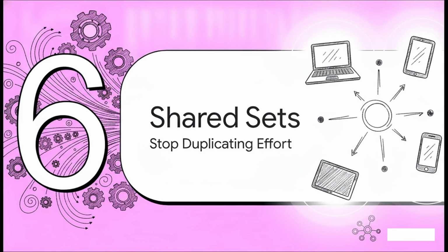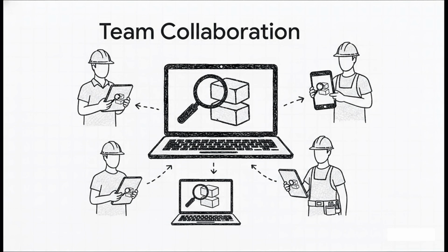Finally, Section 6, Collaborating with Shared Sets. Basically, how to stop duplicating effort across your firm. You really don't have to hoard all this hard work to yourself. Navisworks lets you export your customized search sets as an XML file to share with your entire team. And even better, you can import pre-made sets directly from your specialty contractors.